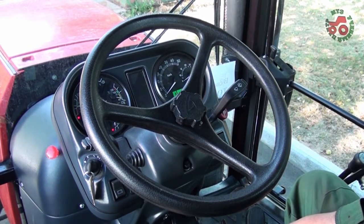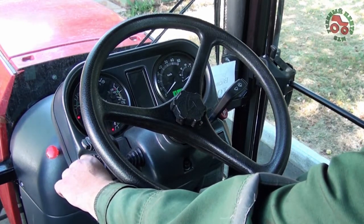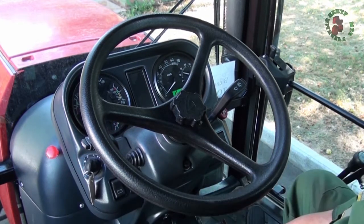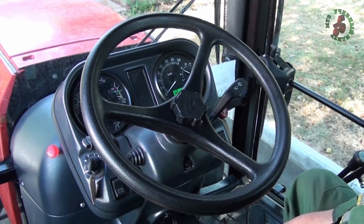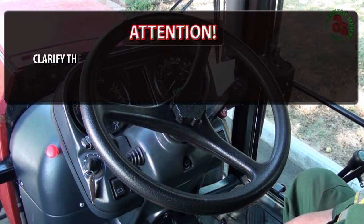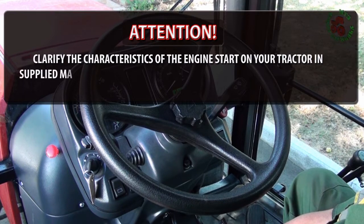The glow plug signal lamp starts blinking or fades, depending on the engine complete set. Turn the key of the starter and instrument switch into position 2 and hold the key until the engine is started, but no longer than 20 seconds. Attention! Clarify the characteristic of the engine start on your tractor in the supplied manual.